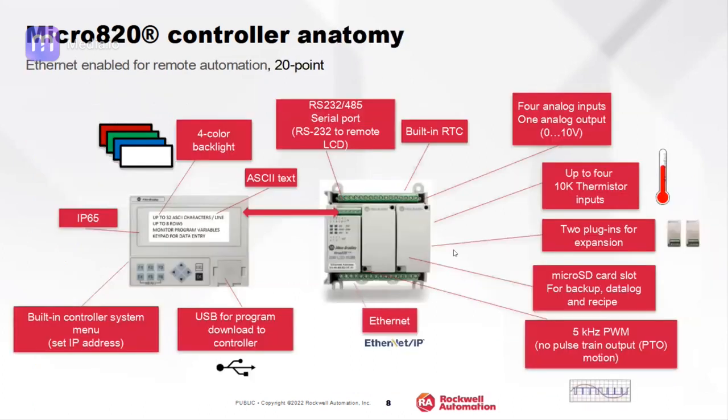So next will be the Micro820 controller. It comes with a serial port and an Ethernet port. This Ethernet port can support EtherNet/IP communication as well as Modbus TCP/IP communication. The serial port supports RS-232 and RS-485.